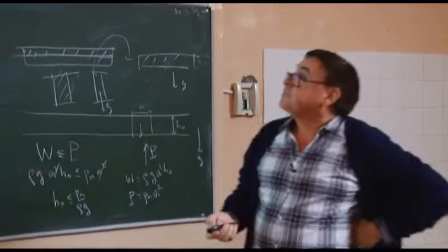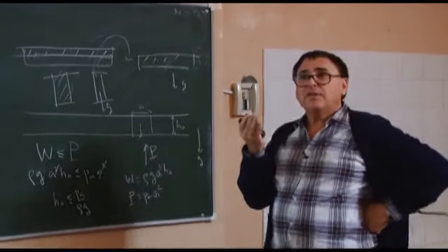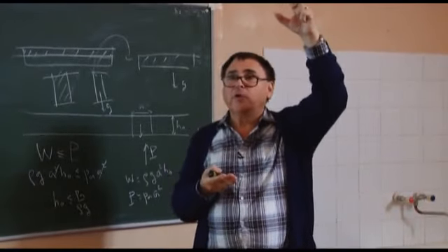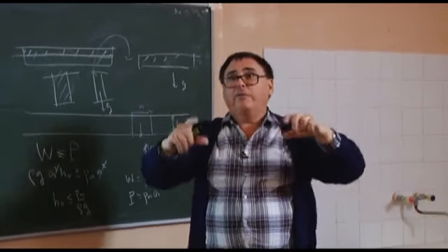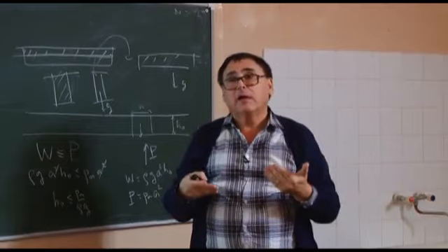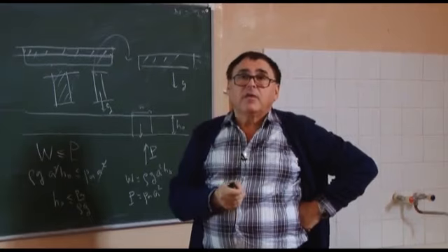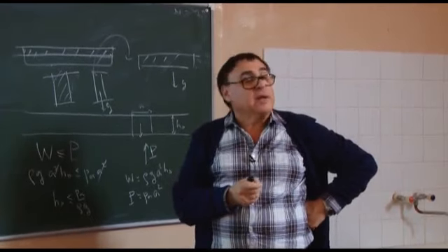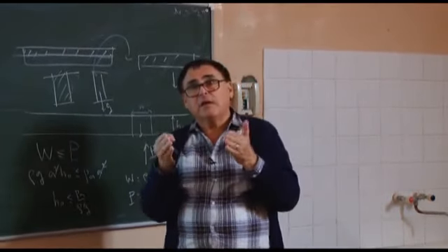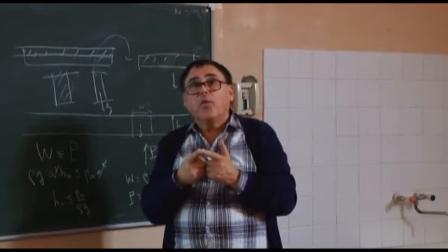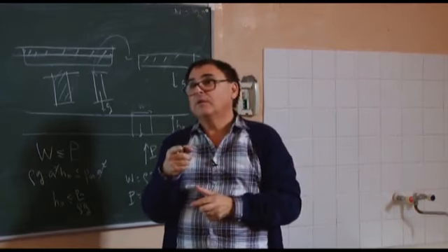Okay, so this is Rayleigh-Taylor instability. Now, seriously speaking, this is the case when you have a heavier fluid on top of the lighter one. That's exactly what happens. You have water above, I don't know, air, or some fluid lighter than water. So that's exactly the case of Rayleigh-Taylor instability. So, maybe generalizing this observation a little bit, Rayleigh-Taylor instability is actually the case where the heavier fluid accelerates into the lighter one.